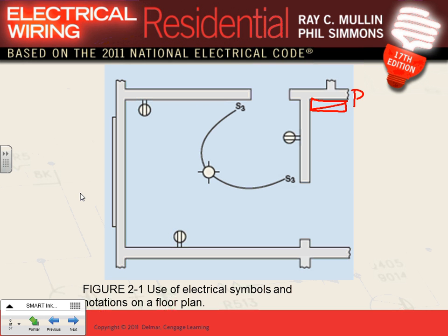And now let's do it as a designer. Everybody knows this symbol of a receptacle. If you don't know, we have a legend. You'll look at the legend. The legend is supposed to tell you what each symbol means. These are ANSI standards adopted by engineers all the time. You're not supposed to memorize all these, but the more you use them, the more you get to know them. So when we design, you put your receptacle. Suppose I want to put another receptacle here and another receptacle here. I designed the power outlets for this room. That's what you guys are going to do with me, except you're going to drop them in CAD.